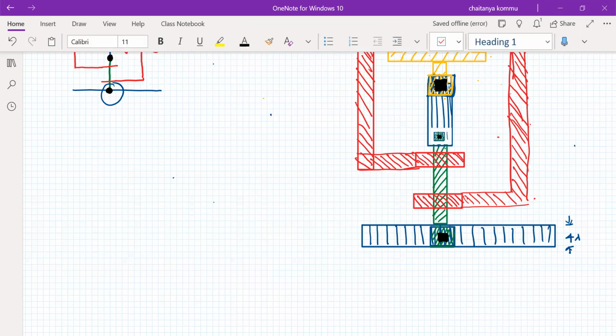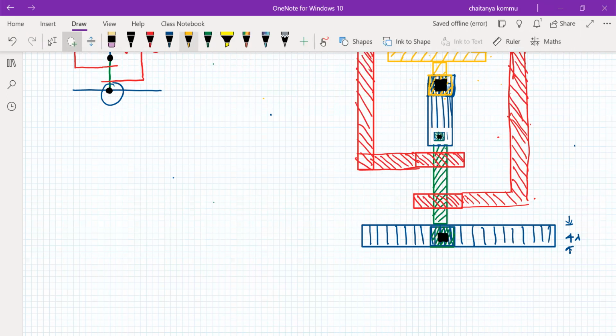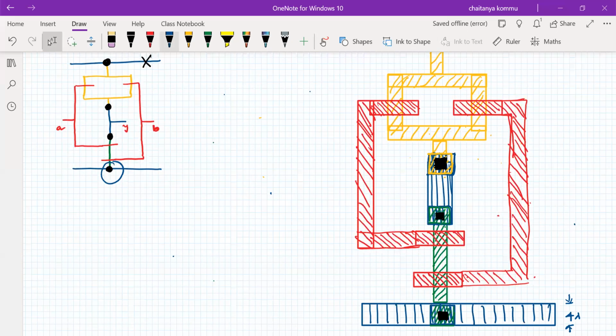Similar contact is required here also, but it is blue overlapped with green and consisting of these lines and the hash lines. At the bottom, the contact cut is required, right? That's it. So we can extend this metal from here to here. The metal we need to extend.